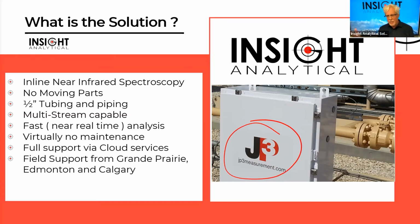They have a rather unique infrared spectrometer, and that's a broadly tuned, a wide wavelength range it can cover laser device, spectrally stable, very bright, very high signal to noise ratios. The beauty of it is no moving parts. So again, we said we wanted something that was going to be transportable. It's nice when something is mechanically robust. We're worried about things like plugging. Well, this is built with big 1/2-inch tubing and piping, not little 1/8-inch pieces of tubing. So mechanically strong, doesn't get plugged very easily.